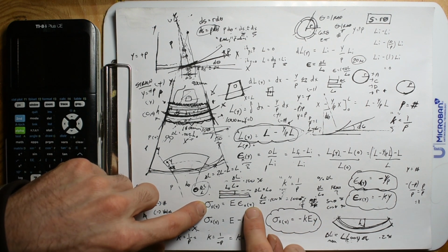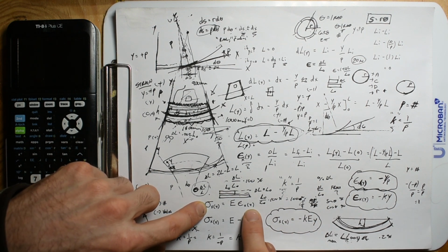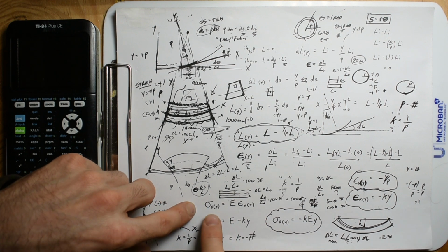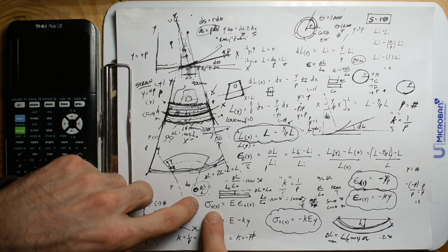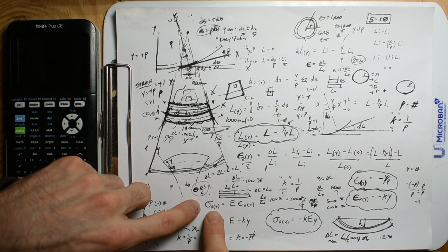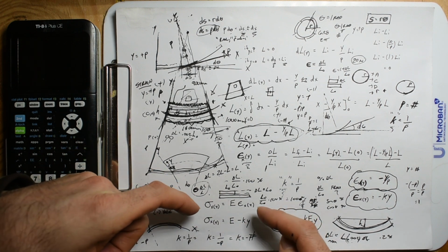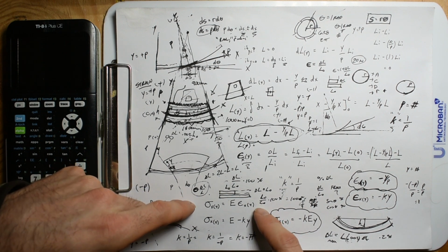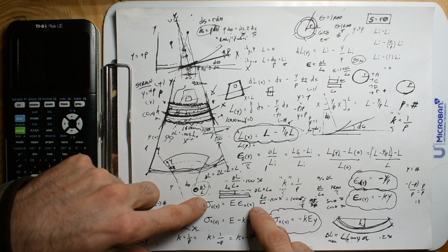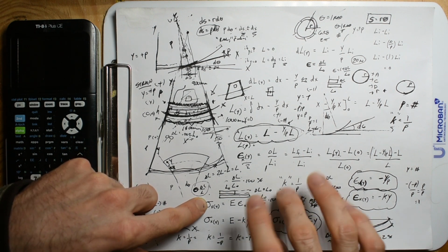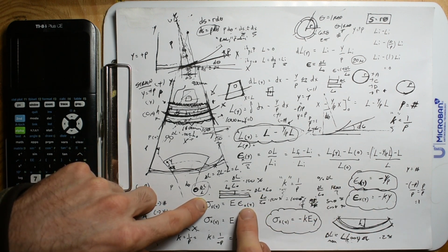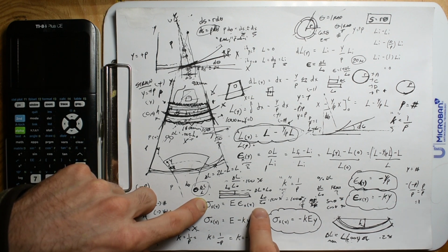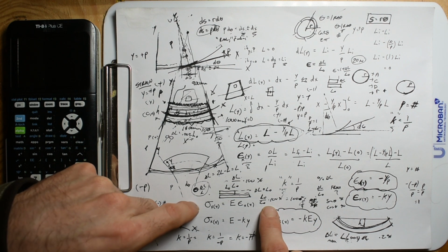This is a material property of steel. It can change its length by 0.002 given your initial length. This can withstand a PSI pressure of 58,000. So we do have two max values, 0.002 and 58,000 for steel. And so those are the max values. If I only change its length by half of the max, or if I only strain this thing halfway, the change in length divided by the initial length is only 0.001, I'm only going to have half of that max.